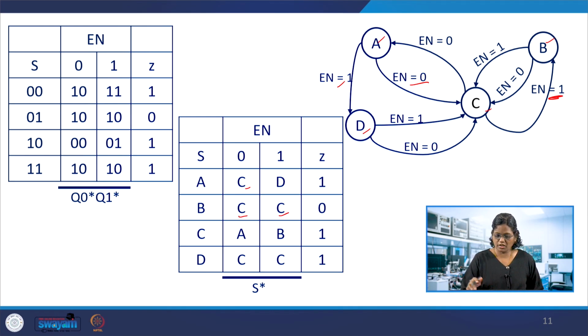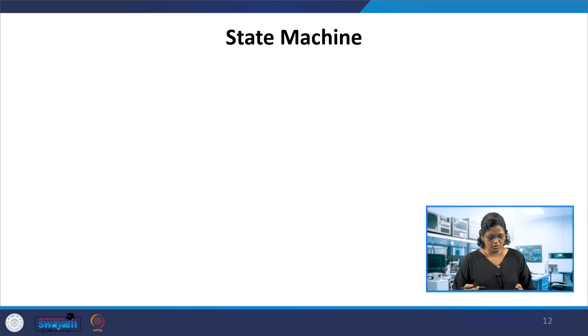Systematically we obtain this step by step, we obtain the state diagram. First identify the excitation equations, and then get the characteristic equations, state transition equations, and then the output equations. After that, make this table and get this diagram. Now with this data, what we have is sufficient to develop the Verilog module. So now let's take the module.